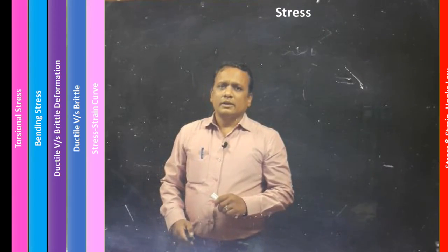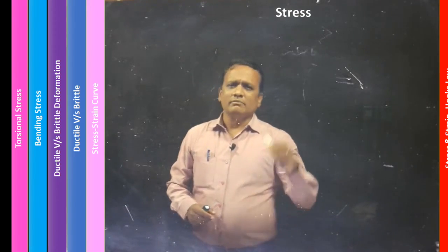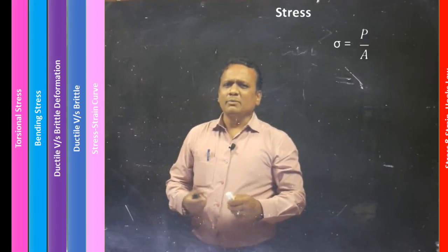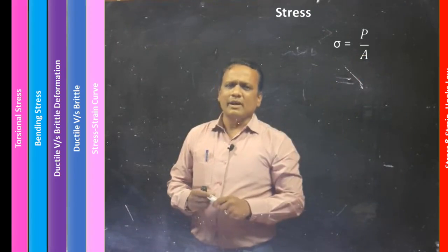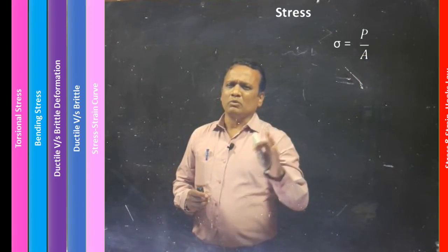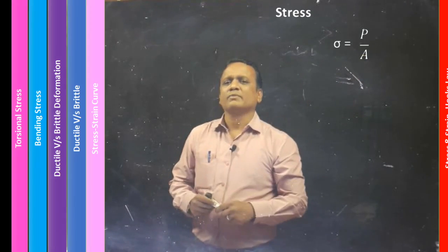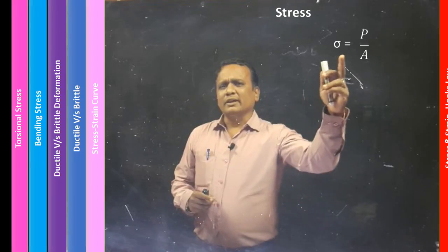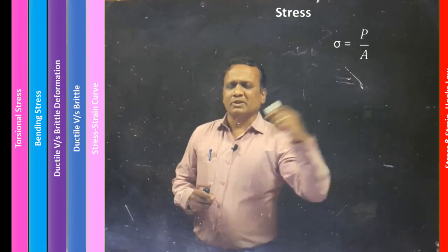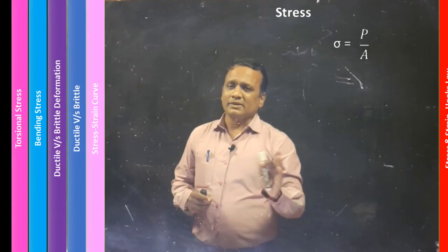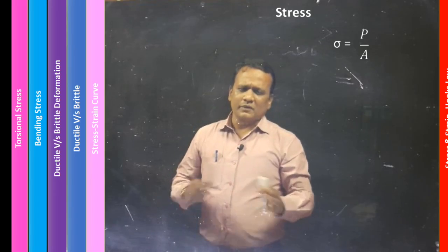So, the concept of stress. You know well that when I say the word stress, the definition of stress plays a vital role. Mathematically, it looks like sigma equals P by A, where sigma is the notation used for stress. Surely you can check that the same equation is replicated with pressure, but that doesn't say that stress and pressure are the same. There is quite a lot of difference between stress and pressure.